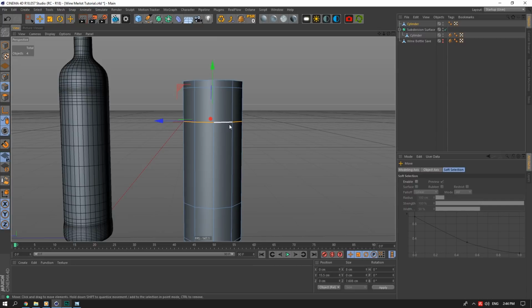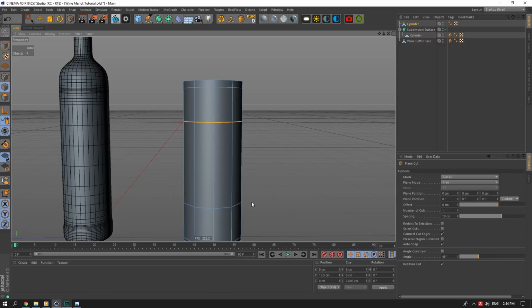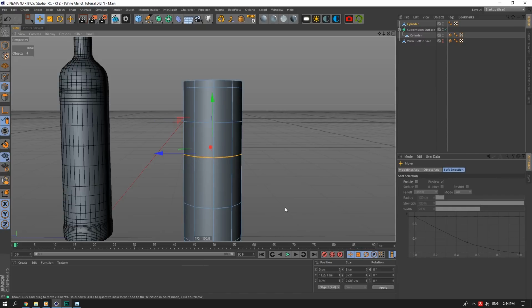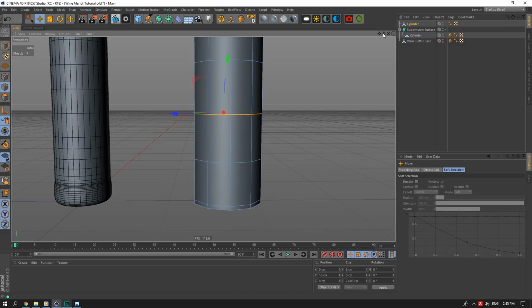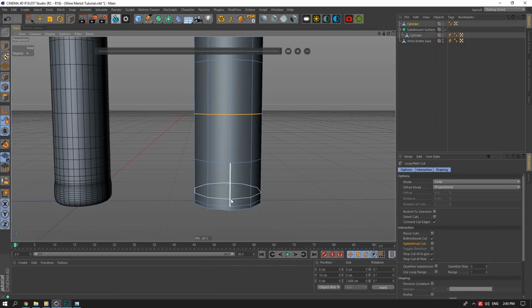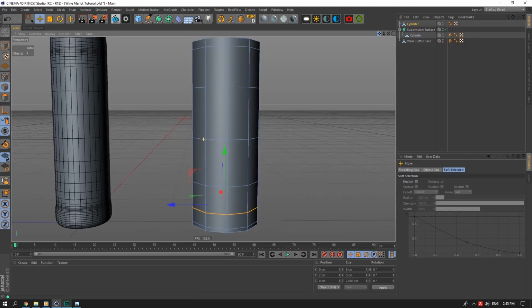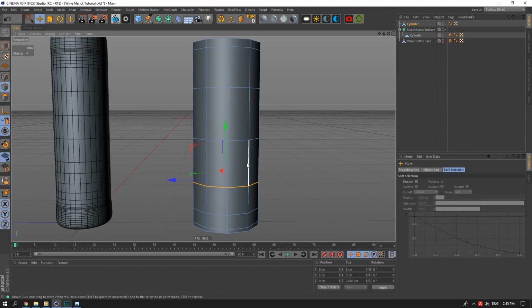And then there's another curve around 10.5 centimeters from the height that curves a lot inside. So if I put a line here and then take the height again and go -10.5, that's where I'll put another line for the glass. And then there's another curve that curves inside around 2 centimeters from the ground. So just to help visualize everything, I'm going to start pulling everything inside so we can see the basic shape of the wine glass.